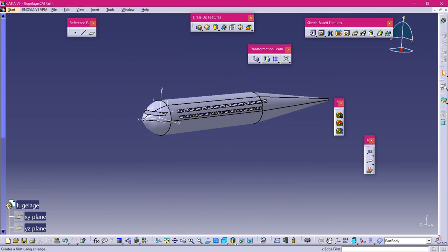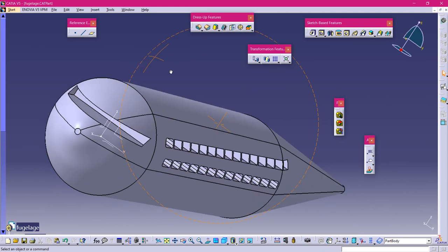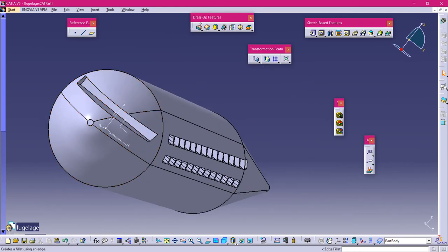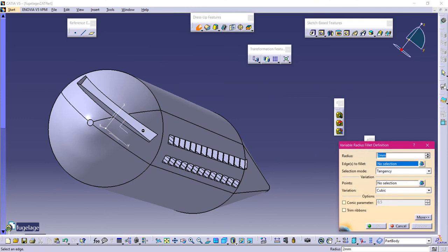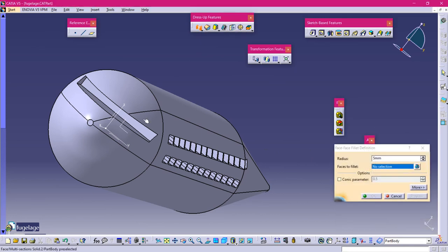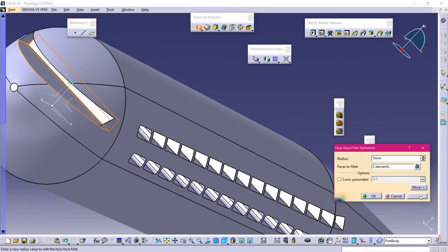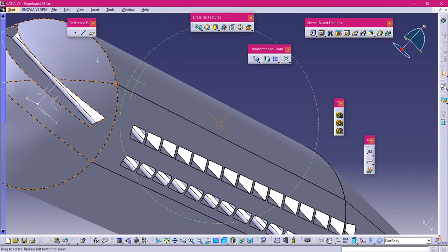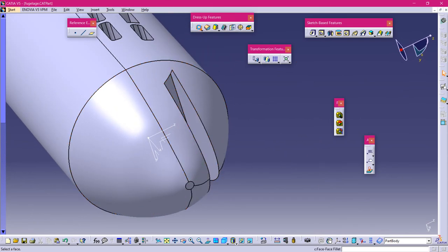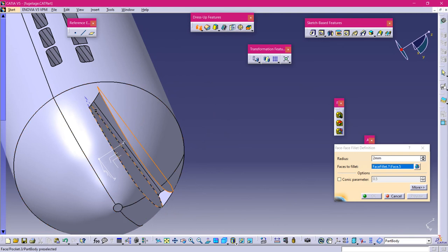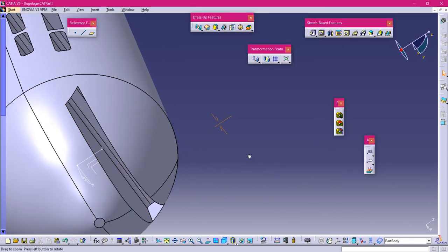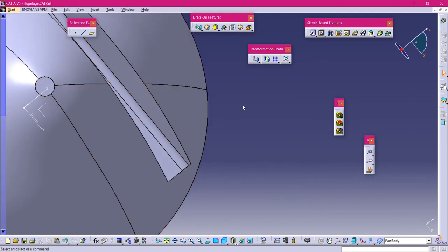Here I have told you the use of this fillet, edge fillet. Similarly face fillet. It can be applied between two faces. For example, let's see, this is a face and this is a face. Select a face fillet. Okay, this is not a face fillet, this is the face fillet. Select face 1 and then face 2. Fillet radius, it's 5 mm. Let's just preview. Oh, it's too high. Let's keep 2 mm. See, a fillet is created between the two faces. Similarly, select face fillet, this face and the face next to that. Fillet radius 2 mm. Okay, you can see fillet is created here.